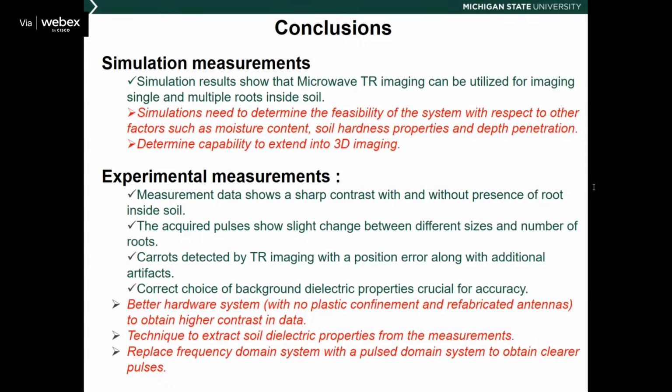As I said, the frequency is not a determining factor for the high resolution, because the resolution at nanometer or micrometer is not determined by the radiation frequency anymore. It's determined by the resonant setup in the near field. So the frequency is still in the microwave range, right? That's why it's called near field microwave, but the sensor is very, very small, so you can get high resolution images.